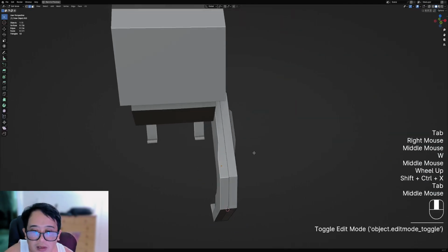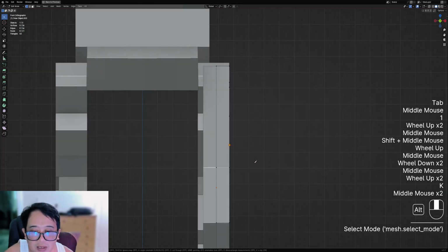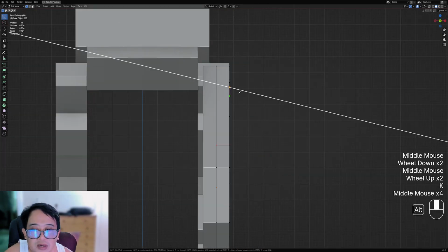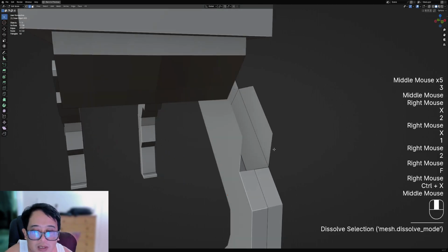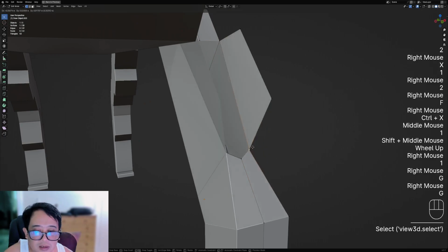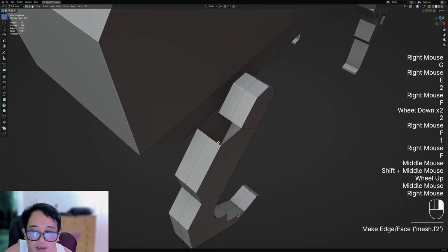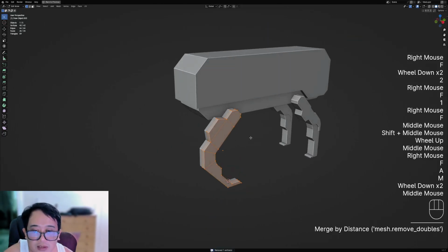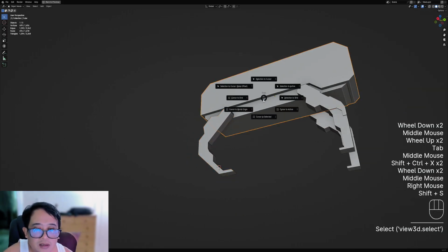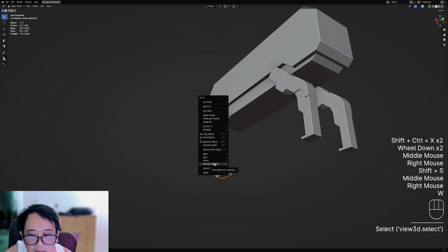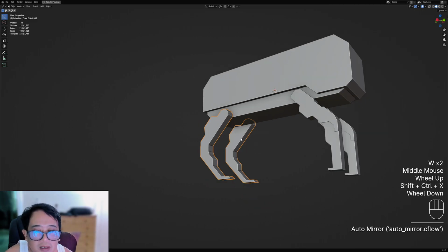Establish the mirror. This. That. And then we can just join these verts here. Click. And then click, change the view, and then do this. And then select this. F. Oh, that's that. Maybe this, maybe this, no, it's not a duplicate. We just do this and there we go. F in the corner vert and then do that. Then Merge by Distance to remove it. Okay. Apply the mirror. Okay. Control click apply mesh. Shift S cursor to selected, then W again. And selecting this object, W, go to set origin to 3D cursor, and reestablish the mirror. There we go.